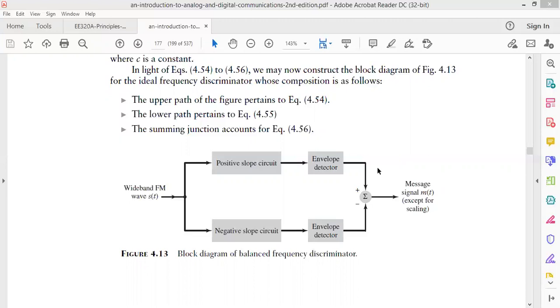So one thing is known as pre-emphasis, which is used to boost up the high frequency component, and on the other hand, when I want to extract the low frequency signal, I need high frequency attenuation. High frequency boost up is done by pre-emphasis.